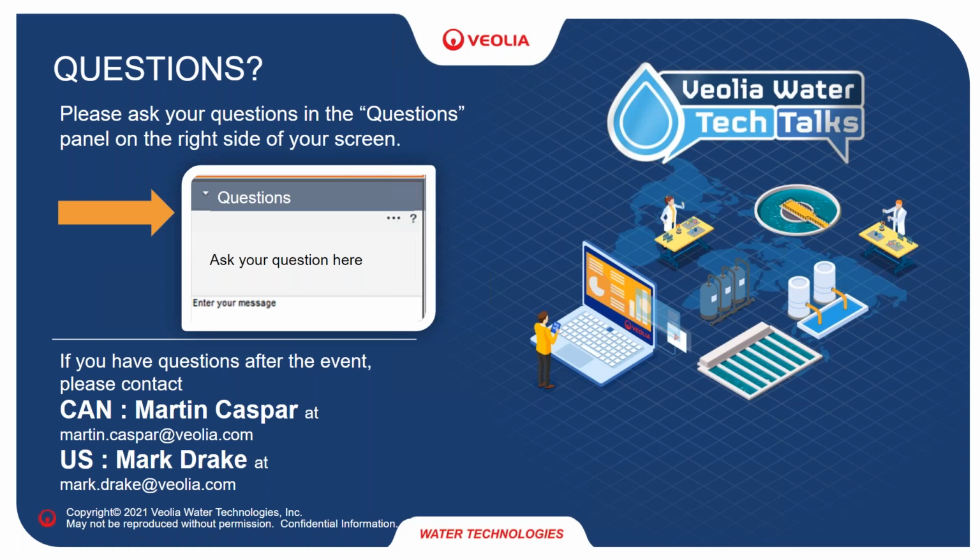So the clarifiers were all designed with 4 meters in diameter less than what a conventional engineering design would dictate, because we knew that instead of building with a little bit of extra size for security, we'll instead build it with real-time control embedded, so that we don't need to build extra concrete, but just integrate a good level of data. So that, of course, meant a lot of savings in total. As we all know, concrete is not exactly cheap.